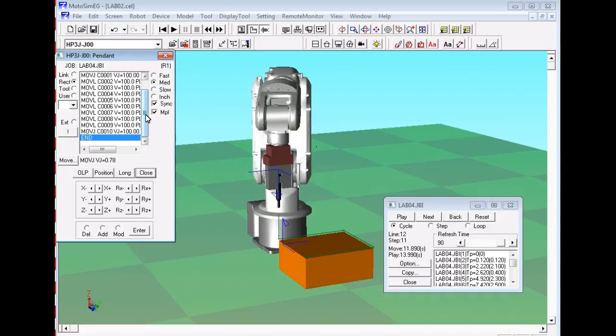Like I said, I did all this at home, and this shows you the world axis down here, by the way. So this shows you the directions if you're using World Jog. This will show you the direction if you're using Tool Jog, which is really, really neat. But the problem is that the tool center point's not right.